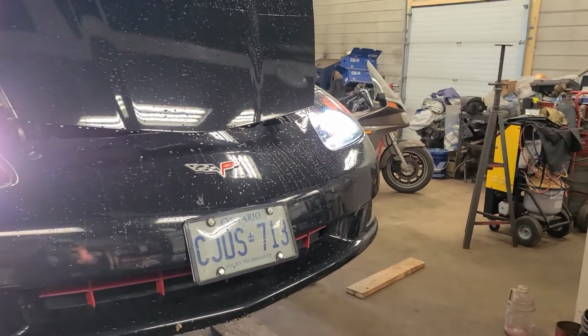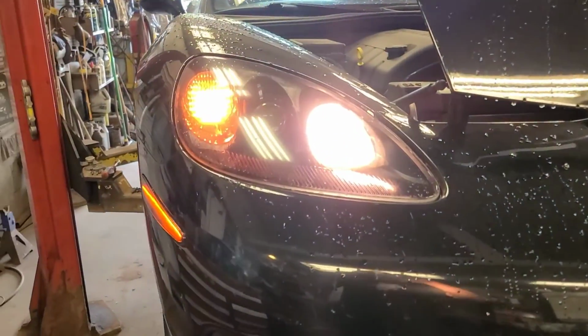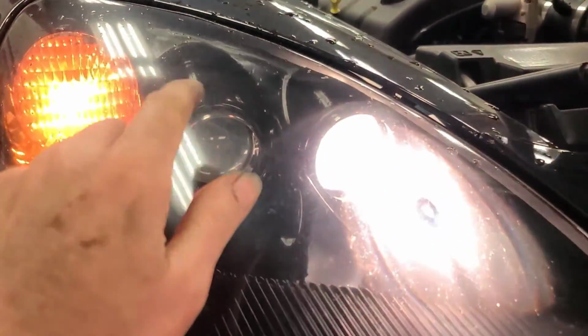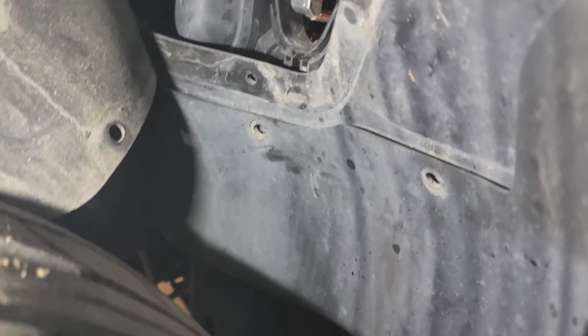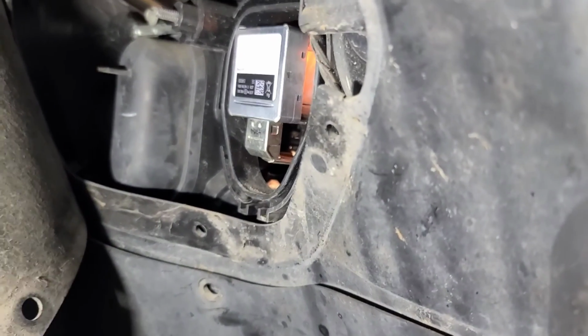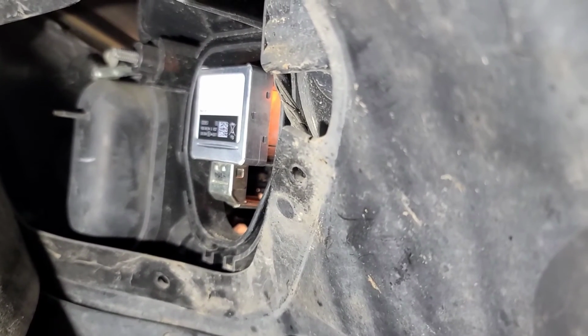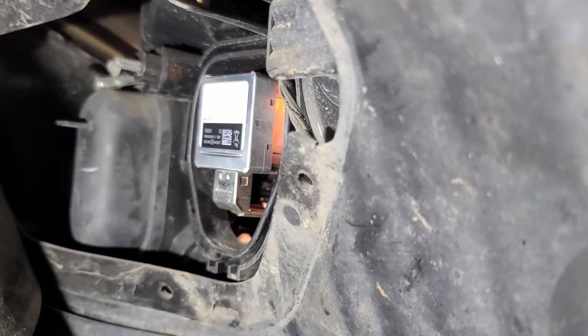So now we're looking at the headlight problem. We got high and low beam on the driver's side. We got high beam on the passenger side, but no low beam. And he says he's changed this. Now access to this bulb is through the inner wheel well. I might have to take this lower one off to get at some wiring here. Now this is high voltage. You got to be careful touching this when it's on because you can get a good zap.